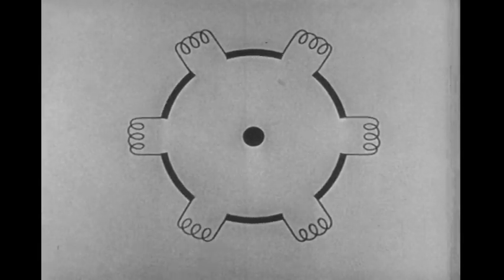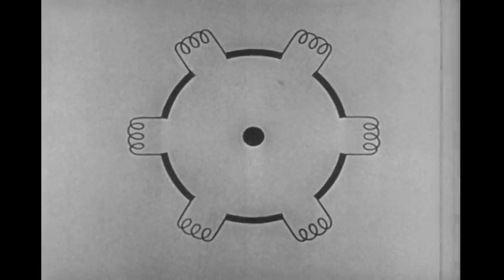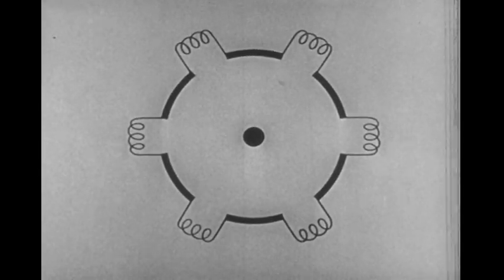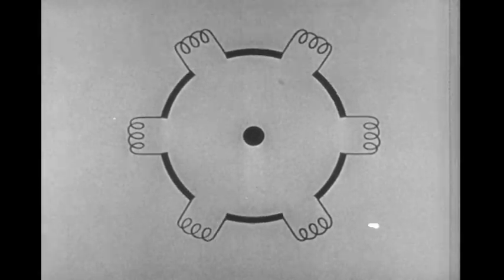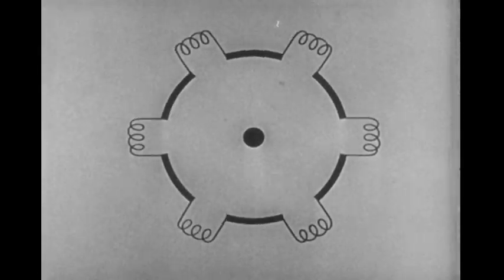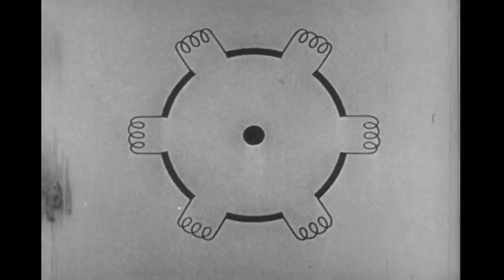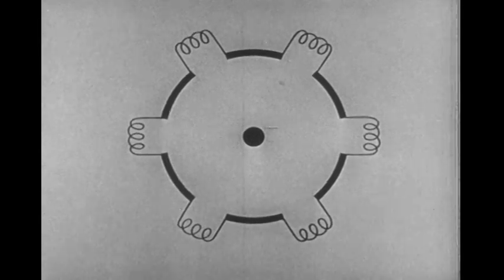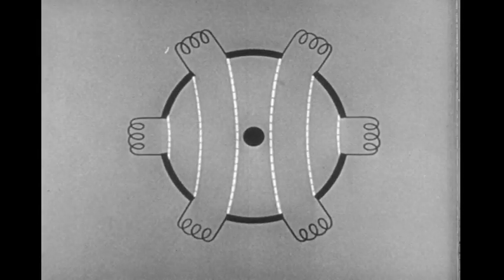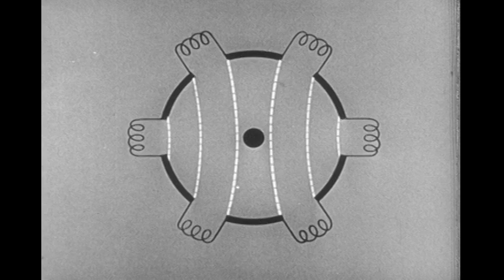Imagine the 6 anode segments of the plane magnetron arranged in a circle around the cathode. The distributed inductance and the interelectrode capacitance form the necessary tank circuit for oscillation in the microwave region. For this reason, magnetrons usually are designed to operate at only one frequency. However, because of the coupling effect between anode segments, 3 frequencies can be excited, each with different RF fields set up. This is one possible frequency with its resultant electric field.